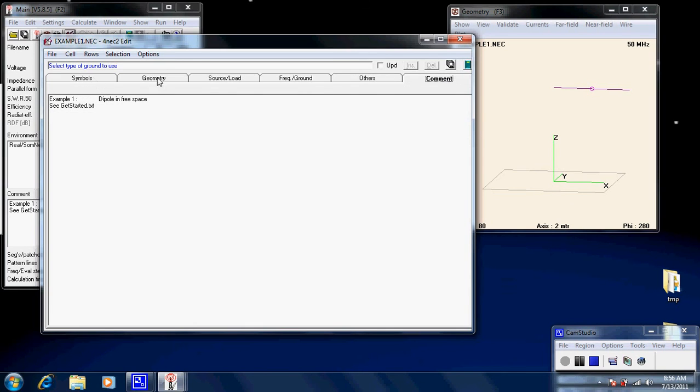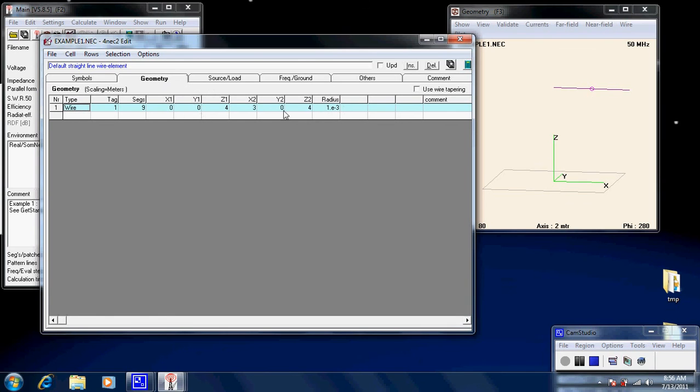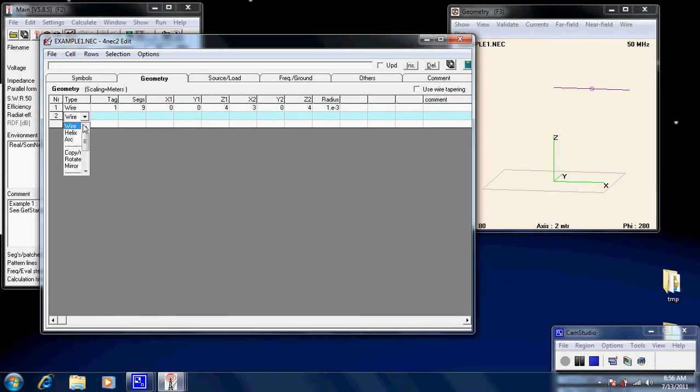Comments again. Now you can go through here and just add another one. We can put in a helix, an arc, or whatever you'd like, but let's just put a wire in. Again, we have tag 2. Let's make it 9 segments. Let's make this 1, 1, and 3. And let's make this 4, 5, 5, and 5. And here we'll make this 1e minus 3, which is just scientific notation for those people who obviously know it.